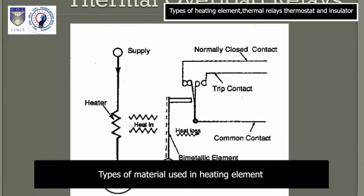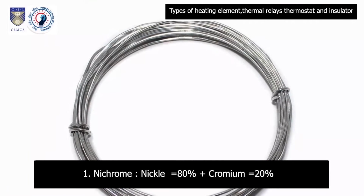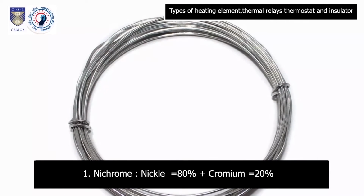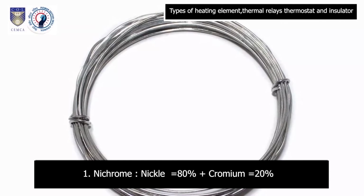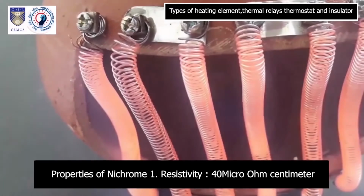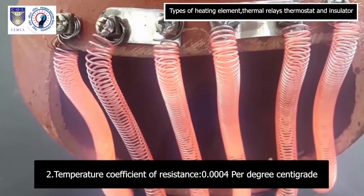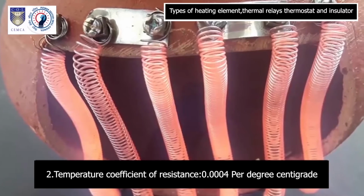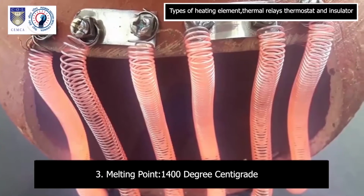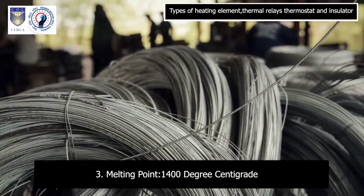Types of material used in heating element. 1. Nichrome. Nickel is equal to 80% plus chromium is equal to 20%. Properties of nichrome. 1. Resistivity 40 microohm centimeter. 2. Temperature coefficient of resistance 0.0004 per degree centigrade. 3. Melting point 1400 degree centigrade.